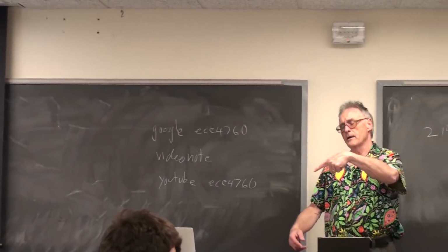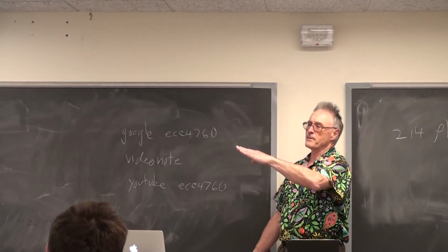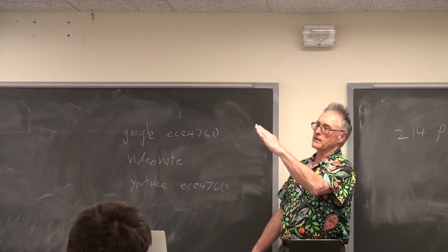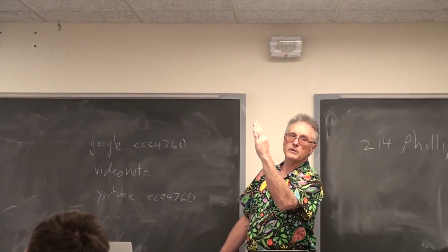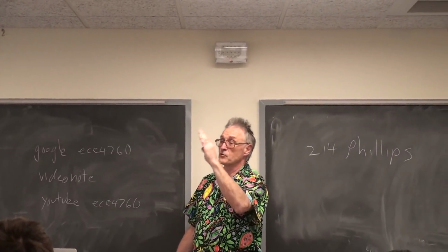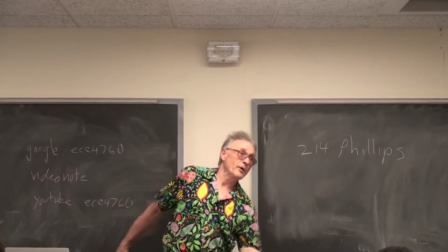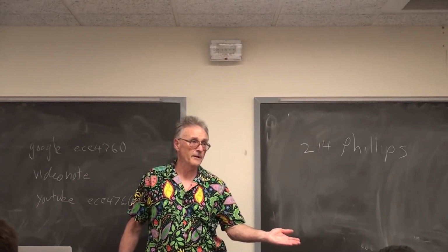And there's a nonlinearity here. You've got this thing that comes up. It's a lever arm. Once it gets past horizontal, as it comes up like this, the differential torque required to pull it further goes lower and lower until it's zero when it's vertical. And so once it starts past the neutral position, it goes whomp and crashes into the table or your arm or whatever happens to be there.